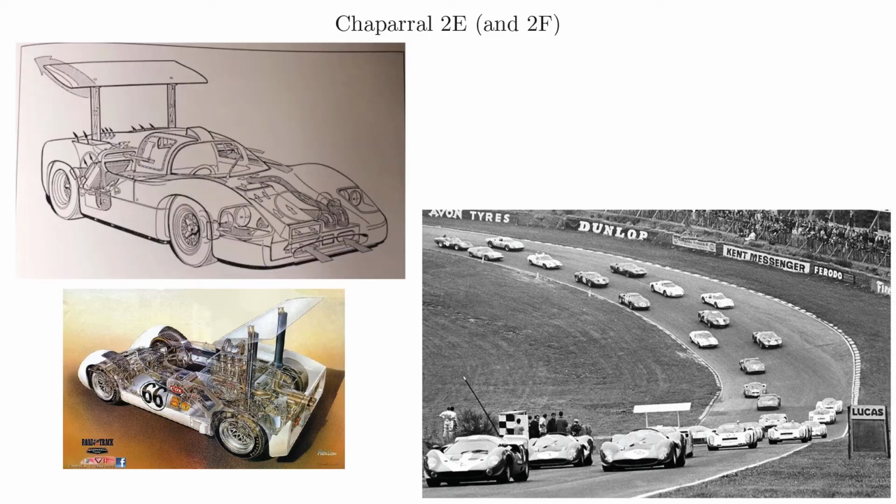Another thing they did, another kind of neat thing we can see on the schematic here, is they moved the radiators backwards, okay? And that helps with some of their heat problems, but also it moves the weight more towards the rear, and they can actually use the air in these side pods here to come over the radiator, which is cooling the engine. So when he first brought it to the track, the story is that a lot of people laughed at him, but as he puts it, maybe let him put it in his own words here.